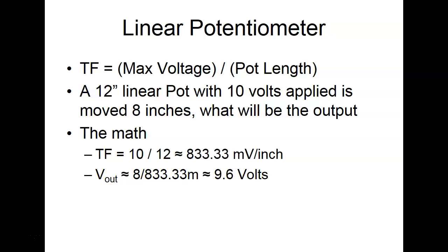So 10 divided by 12 is 833.33 millivolts per inch. So I take that and multiply it by the number of inches, and I would get 9.6 volts. Are we okay there? Yes, no?